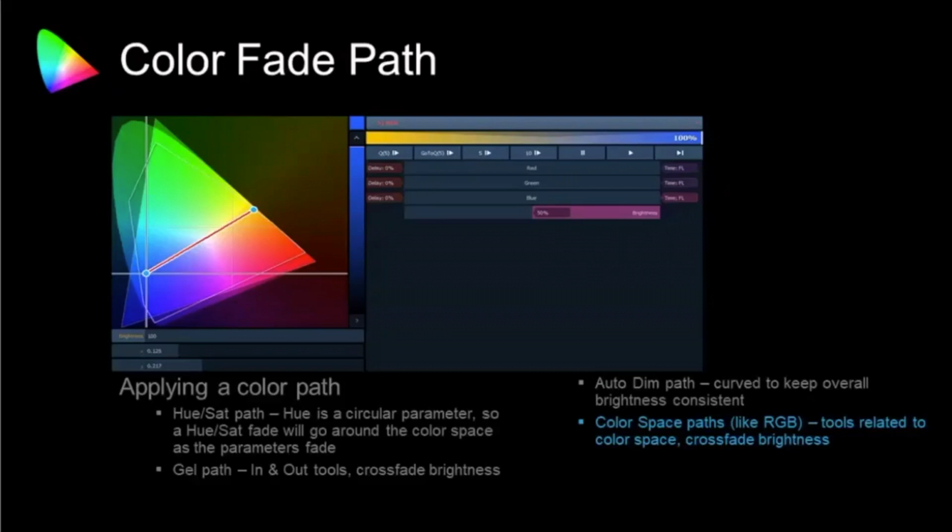So use these spaces. If you're crossfading across white, sometimes that white can be really bright in an LED and really undesirable. I'll use this fade path, not because I actually want to adjust the RGB or because my fixtures are even RGB, but because I want to move away from the green just on the magenta side of white. So consider that if you're passing through white.